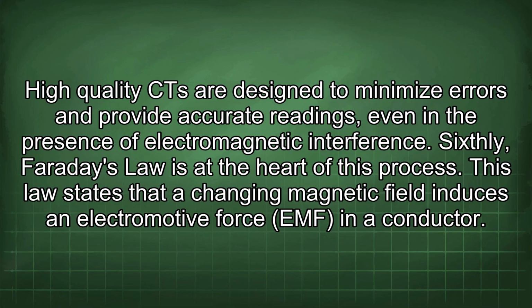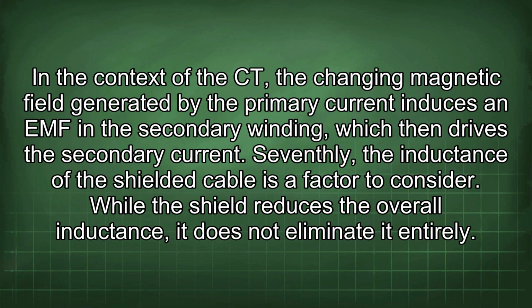Sixthly, Faraday's law is at the heart of this process. This law states that a changing magnetic field induces an electromotive force, EMF, in a conductor. In the context of the CT, the changing magnetic field generated by the primary current induces an EMF in the secondary winding, which then drives the secondary current.